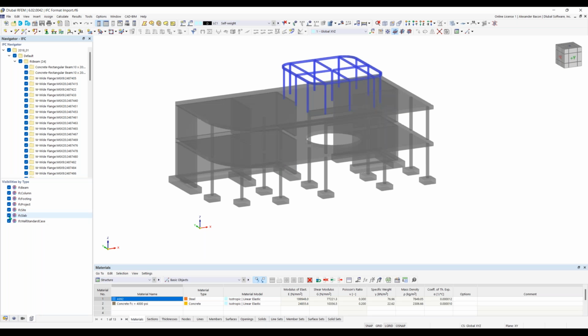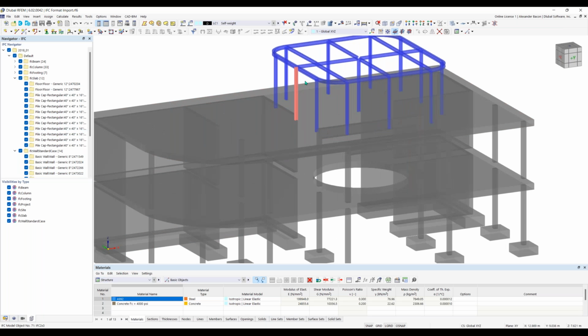And we're able to turn on and off the slabs here. So there are some visibility types automatically created. We can turn on and off the visibility of the columns along with the footings here. So you have some options for visibilities, and then you can also get even further into detail with visibility by turning off specific objects. So you can turn off specific columns, beams, columns, and footings.